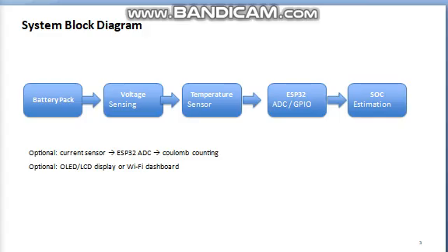So directly the output of the temperature sensor is connected to the ESP32. The pin which connects the temperature sensor with the ESP32 is called the ADC pin. It is also one among the general purpose IO pins, an IO pin with analog interface facility that can read analog inputs.